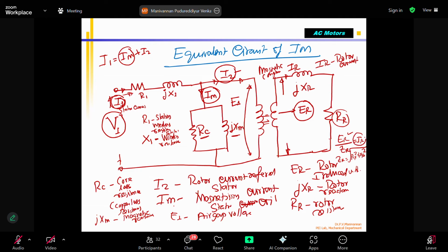For IR, we use voltage divided by ZR, and ZR equals the square root of resistance squared plus reactance squared. But one part you have to know is that XL equals 2πfL. But R does not depend on frequency. So if your supply frequency varies, the reactance varies, but the resistance never varies.